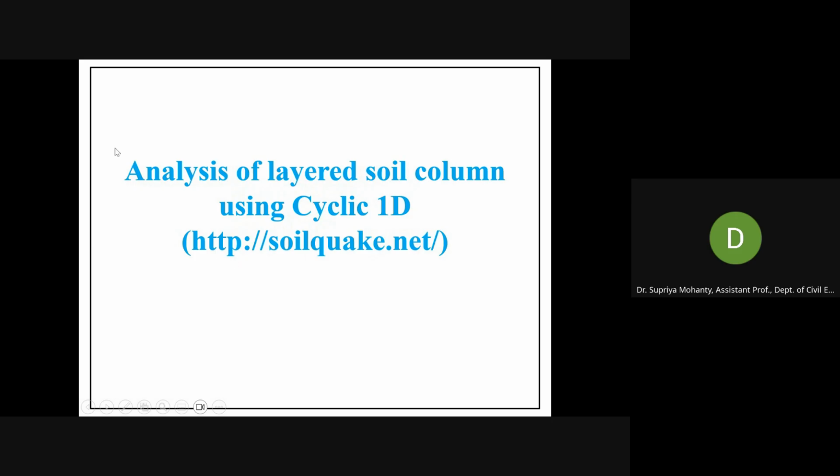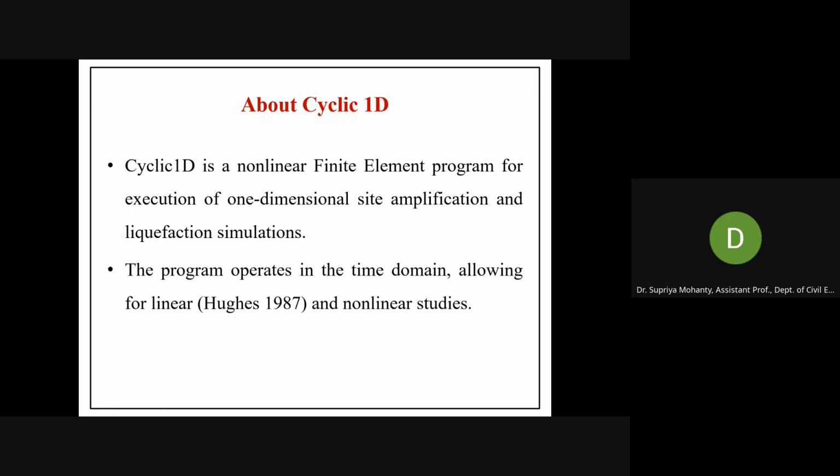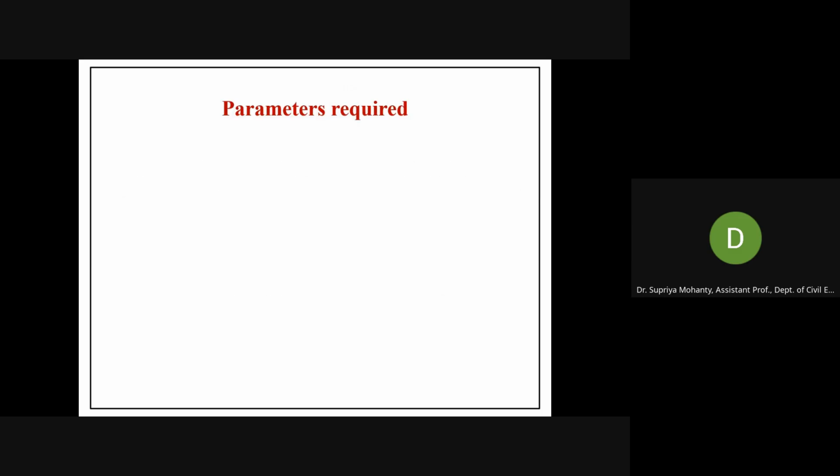You can get this Cyclic 1D from this website. If you just write soilquake.net, there you will get the setup files and a link for installing Cyclic 1D, and it is very simple and user friendly also. Particularly, this is a nonlinear finite element program for 1D ground response and site-specific amplification and liquefaction simulation. And an important thing is it operates in time domain. You can consider the exact time history also while analyzing.